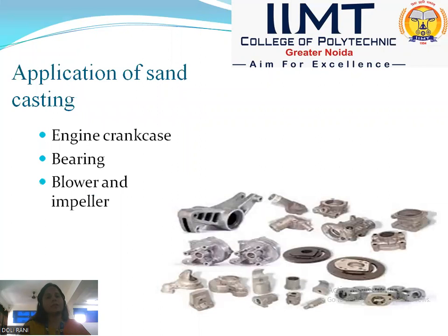The application of sand casting. Sand casting is used in every field. Suppose in the automobile industry, we can prepare an engine crankcase by using this process. We can prepare bearings, blowers, impellers, turbine parts by using this process. And mainly the lathe bed is prepared by using the sand casting process. Why? Because it has a very simple process, and the loss of metal is very less as compared to other manufacturing processes, and ease in manufacturing.